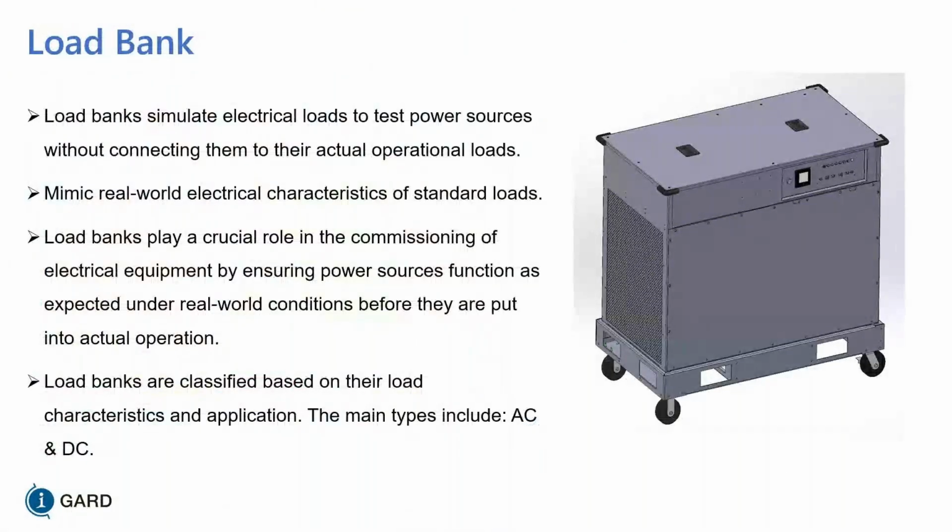So basically, a load bank simulates electrical loads to test power sources without connecting them to their actual operational loads. So if you have a generator or a power source like a UPS and you wanted to test it under full load conditions, you would probably use a load bank because you can't really simulate the loads unless you can guarantee that there's going to be constant load on the source at all times.